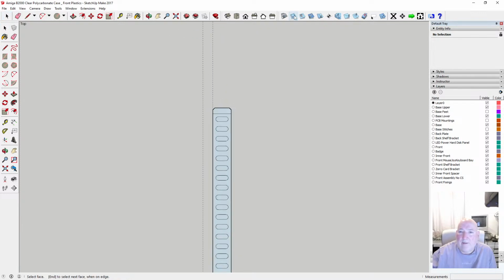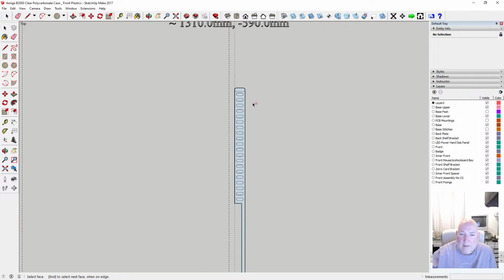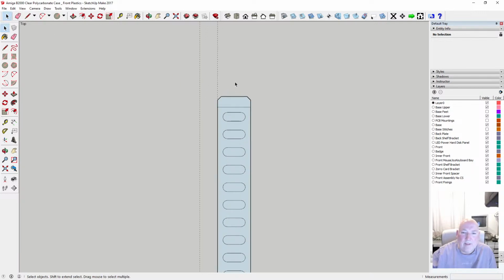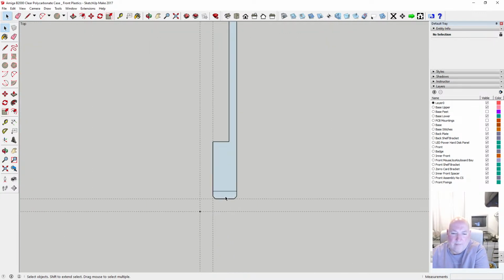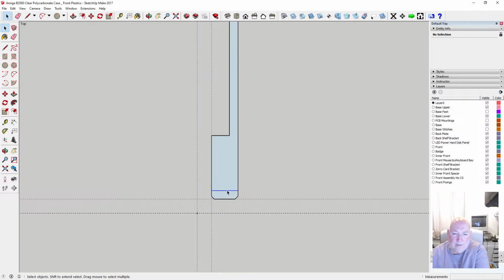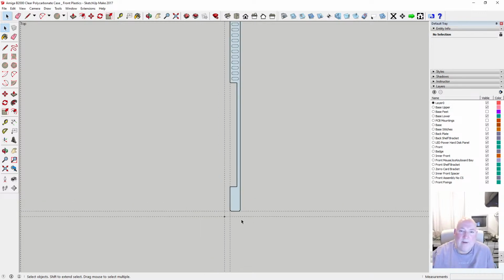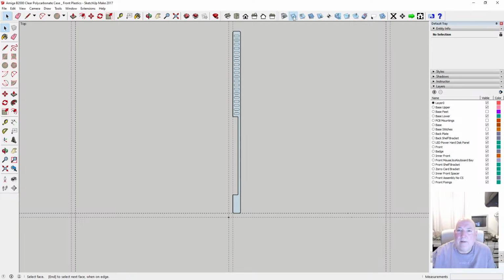If we try to do an outside cut, it's not going to like the pocket. So we need just to get rid of the marks that indicate the pocket. So just want an outside cut all the way around it. Here we go. So outside cut, that's bang on what we want.